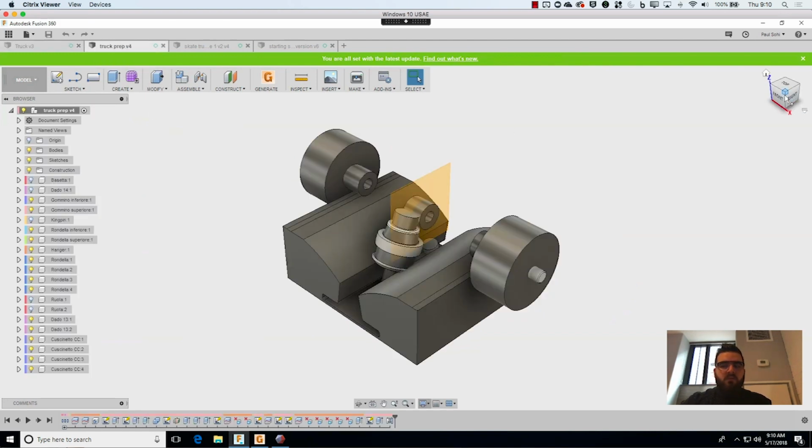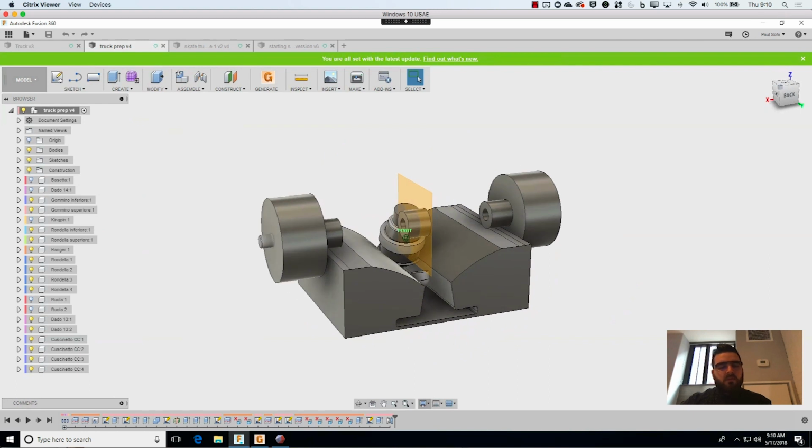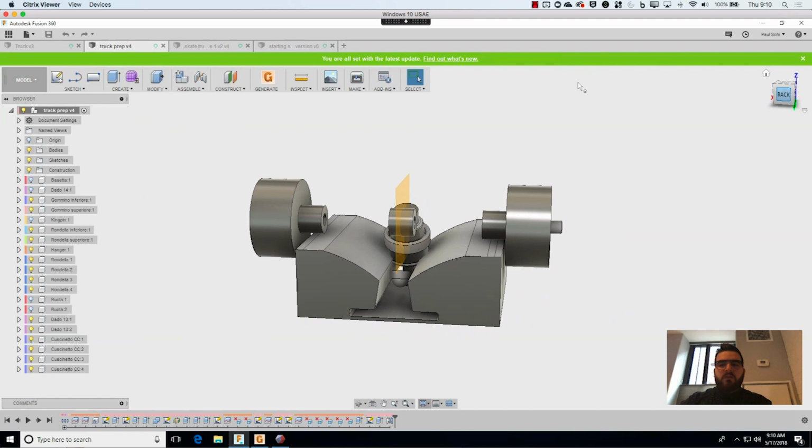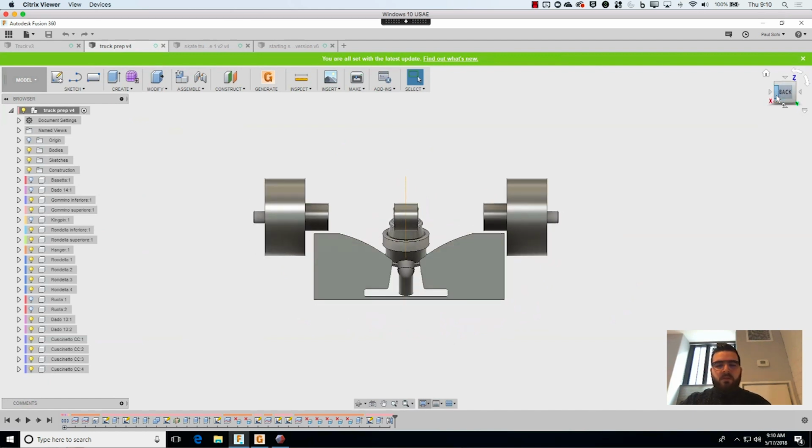Now, when you're designing with generative, you have two things to remember. You have obstructions and you have preserved geometry. Preserved geometry is essentially where you want things to be connected up, where you want the focus of your geometry to be. And the obstructions are, well, they're obstructions. They're there to prevent the geometry from creeping into areas where you need to keep it clear.